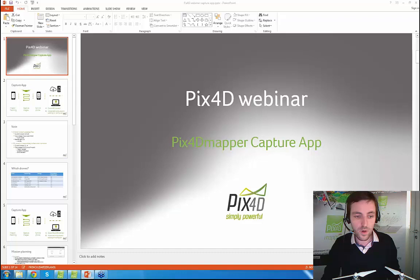And for the Inspire 1 and all the other drones, the geotags will be also nicely supported. Now the good news is that even if you don't have the optimal flight plan and the geotags are not there, already now all the images can be processed in Pix4Dmapper. So the desktop software supports all of these images. However, you have a better chance of better accuracy and better reliability of the results if you've done it through our app, or if you read very carefully what are our requirements and our suggestions for optimal flight paths.